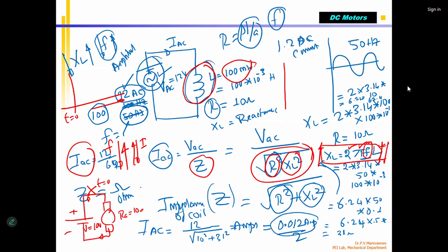Yeah, the IDC or IA armature coil current, because your DC motor is going to be 10 divided by 10 ohms, 1 amp current should flow. But please note, they have a beautiful, important question. The DC motor armature also has a coil, so coil inductance comes in, which means you need to consider Z only. Even for this, it is VDC divided by Z only, because my armature is a coil. So it will be VDC divided by root of R square plus XL square.